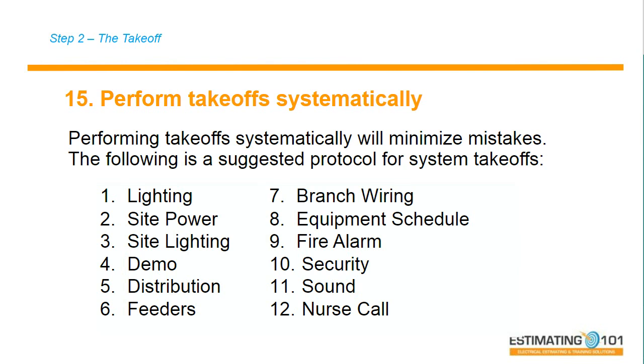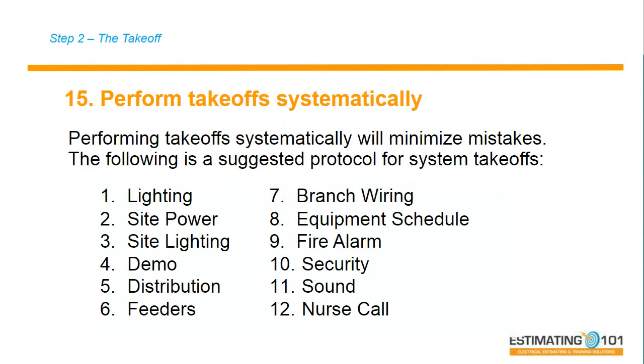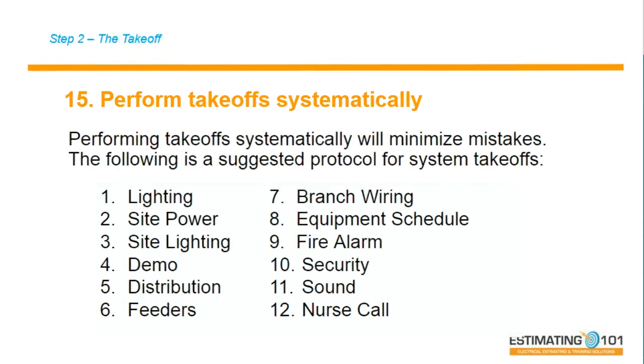How many times have you, if you're an estimator, said after you finish, I'm going to review the drawings one more time to make sure I got everything? Well, you're wasting time. Don't go back one more time. Get it all the first time by systematically making sure you complete every drawing as you move through the estimating process. So it's vital that you estimate systematically. Again, you may not like this protocol. Develop your own protocol that works for you and follow it every time.